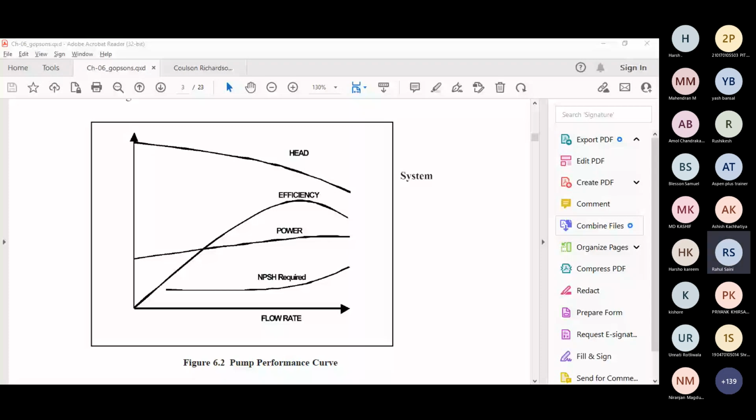Yeah, that's correct. That 6 kg suction pressure is just an example. It can be provided by another pump, or you can shift the overhead tank up to the 10th floor. So anyhow you can boost the suction pressure. Increase the height of the tank, right? So that can be done. It depends whether the pump has positive suction or negative suction.